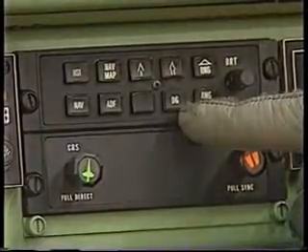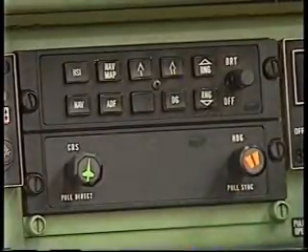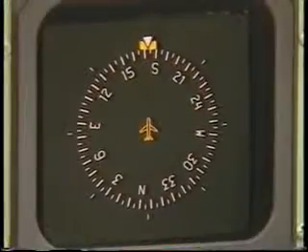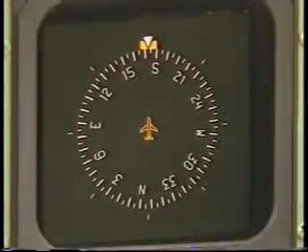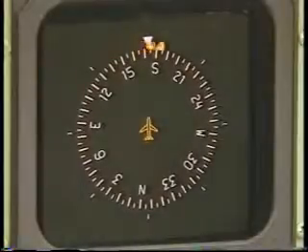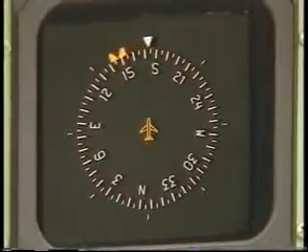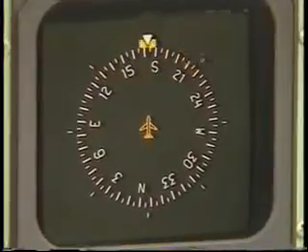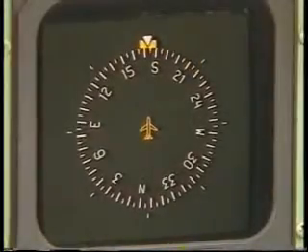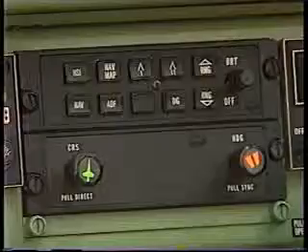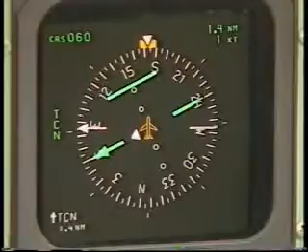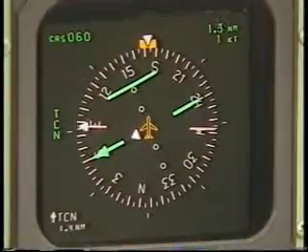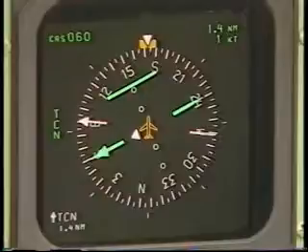DG is the raw instrument mode, and no radio aid information is available at all. With DG, only the compass card and heading bug are shown, a very uncluttered display. Also, with DG, the only warning flags which will appear are the attitude and heading flags. If DG is pressed twice, the display returns to the HSI format. A special point to note here is that with the localizer, the single white RMI pointer disappears. They are the mode buttons.